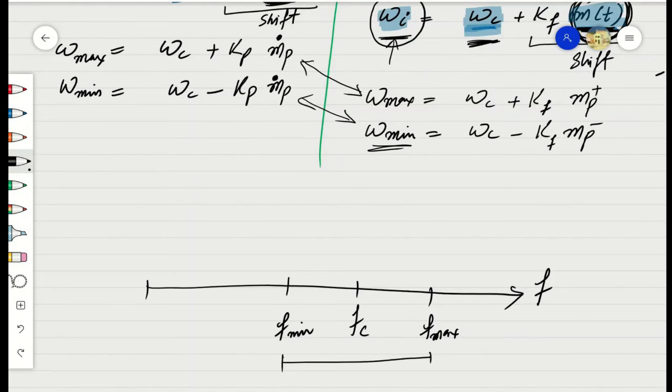So roughly, the bandwidth consumption for both the modulation schemes can be analyzed from these expressions, where it can be observed that the shift caused in the carrier frequency is proportional to the amplitudes of the information signal and the constant scaling factor which was being multiplied with the information signal.